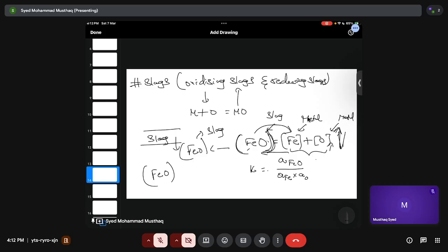And FeO can even react with some of your impurities. So in basic steel making, whenever you lance with oxygen and purge air into your liquid, it will form foam, an emulsion.